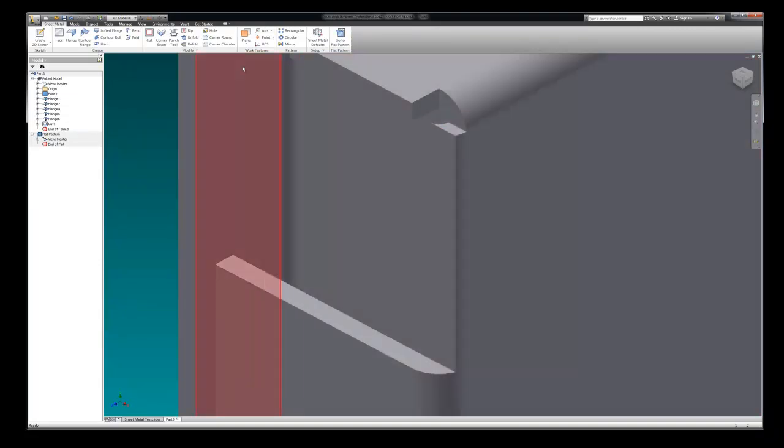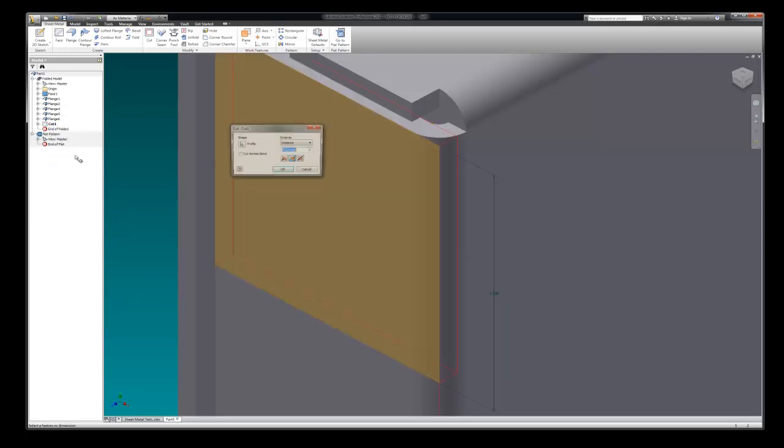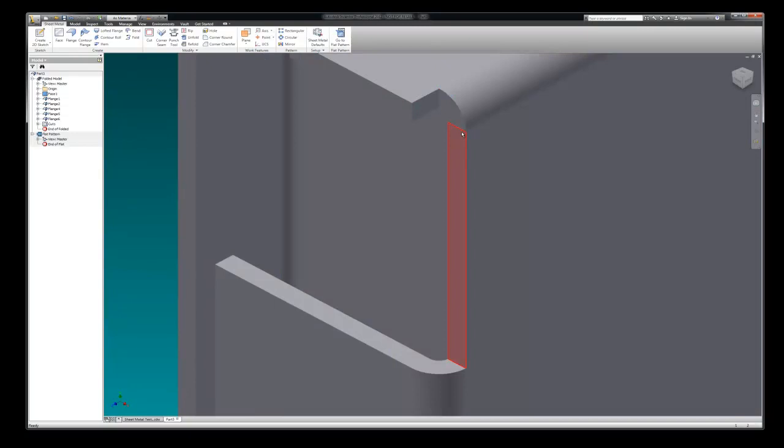Now I can get rid of that. All I have to do is go back into my Cut tool here, right click, and go to Edit Feature, and I change the depth now. I'm going to go like 0.18. Let's see what that does. Great, it almost took it right down to this point right there. So that got that out of there, and that looks really good.